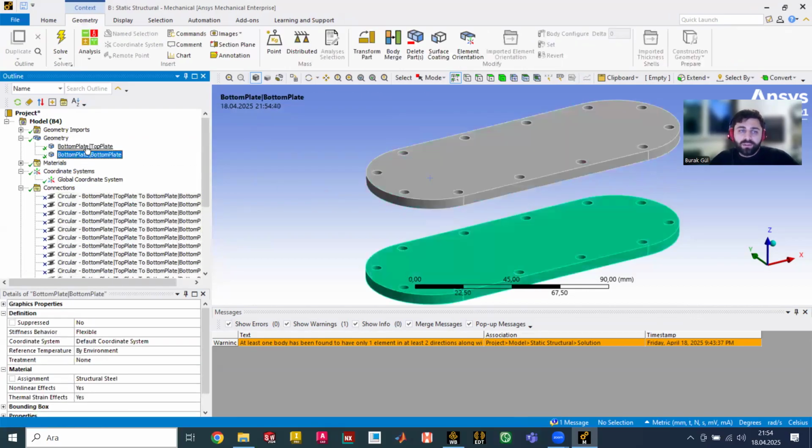Here, the two plates are in the same file, but they are not merged. The bodies are different. When you create them, please create them in two different bodies. The first body you can create directly, then you can create another layer and create another solid by using another drawing on this one. After creating it, you shouldn't use the solid command as merge. Don't check the merge button in the design. You will understand when you try to do it.